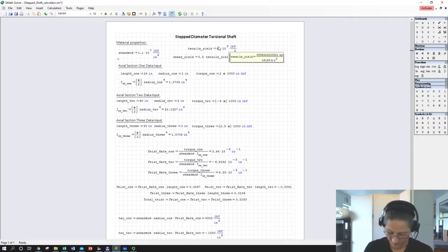For the same material, I've gone across and I've noticed it has a range of yield strengths, and that corresponds to the processing. So depending on whether it's annealed with big grains, or it's been cold worked, or it's been heat treated, there's a huge range of yield strengths going from 30 to 160 ksi. I've decided that nobody's probably going to make a torque conversion shaft, which is something that has to have a certain minimum level of strength, out of something that's necessarily on the low side. If I were going to something with a higher fracture toughness, I might want to go to a grade of stainless that had a lower tensile strength,